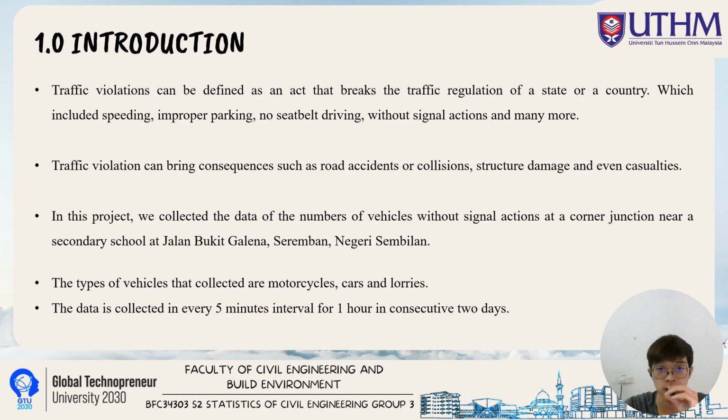In this project, we collect the data of the number of vehicles without signal actions at the corner junctions near a secondary school, which is located at Jalan Bukit Gamina, Seremban, Negeri Sembilan. The types of vehicles collected are motorcycles, cars, and lorries, and we collected the data at every 5 minutes interval for 1 hour on 2 consecutive days.